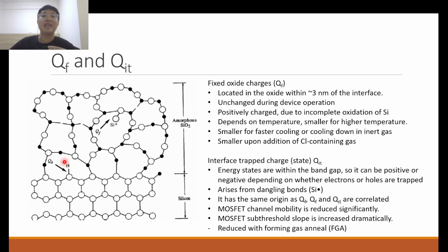a single unpaired electron. When a single unpaired electron is there, it can do two things. Firstly, it can attract another single electron to go together with it and form a lone pair, and that is the idea of trapping an electron. So the radical is there, and it traps a free electron from somewhere. After all, you're applying some voltage, I presume, when operating the device. So it traps the electron, and then it becomes a lone pair, and that is considered an electron trap. At the same time, if there's an electron acceptor somewhere, the radical can give off that single unpaired electron, and effectively it's acting as a hole trap.